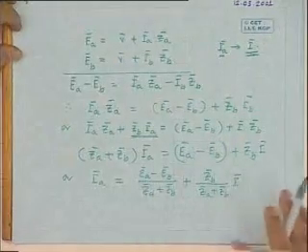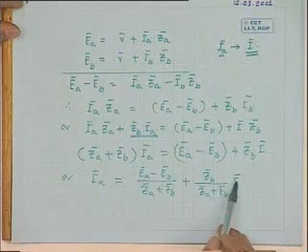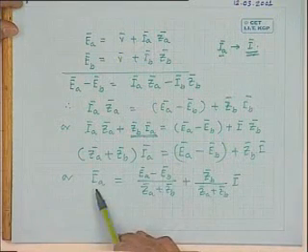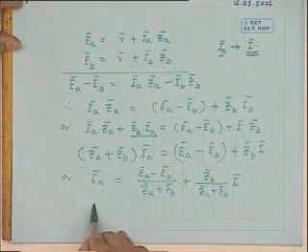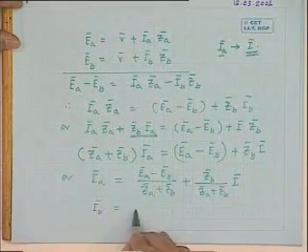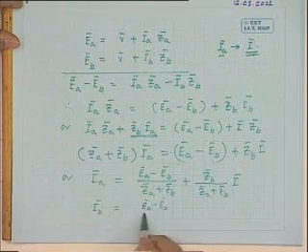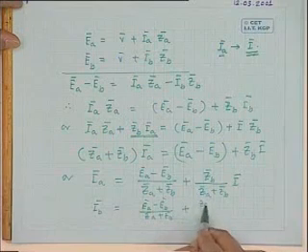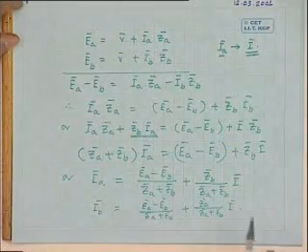See, obviously, if the voltage ratios were exactly equal, then this term would have been 0, and this is just the parallel impedance rule that determines how much transformer A will carry, ZB bar by ZA bar plus ZB bar. In the same way, you can show that IB bar will be just the opposite: EA bar minus EB bar by ZA bar plus ZB bar, preceded by a negative sign, plus ZA bar by ZA bar plus ZB bar into the total current.